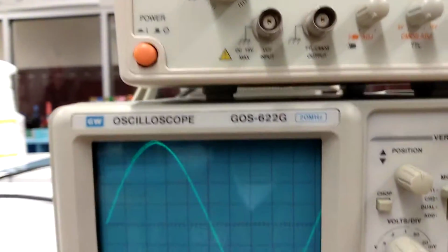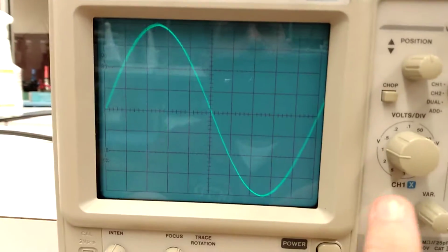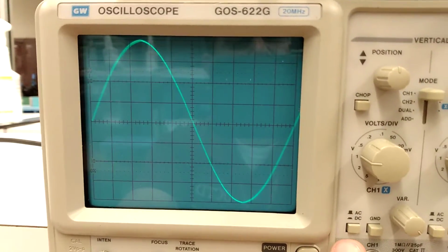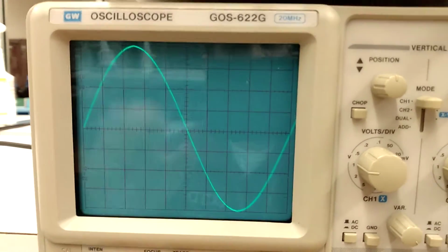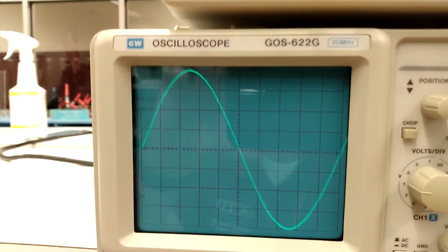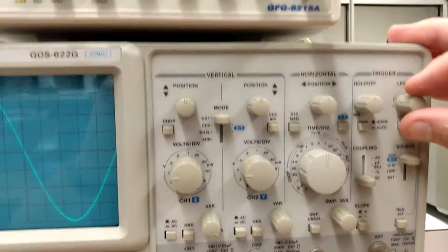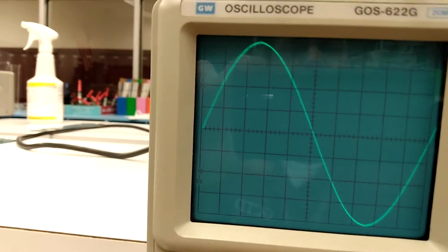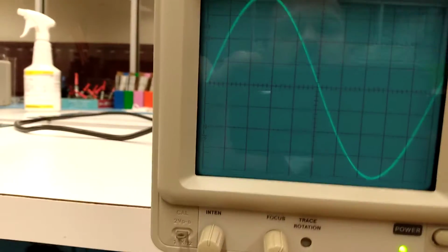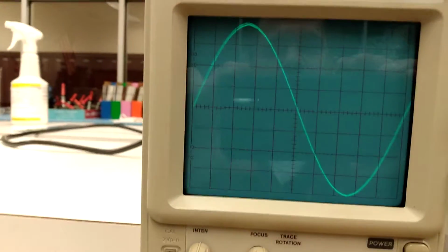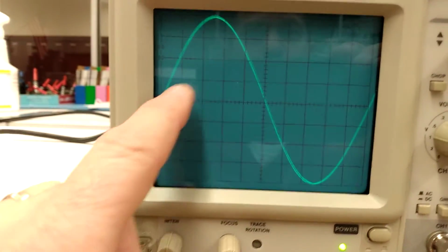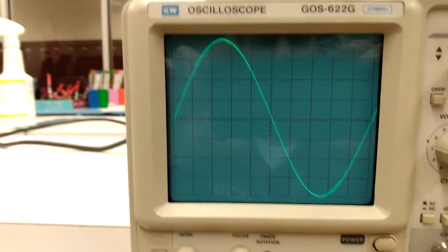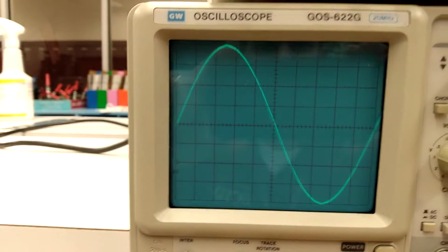And when we look at our oscilloscope, which has been set up now at 1 volt to the division, we've got a DC offset, so we're splitting our signal in the middle. Using our trigger level here, we've adjusted our pickup level so that it is right at the 0 mark there. And looking across, counting your number of squares, 1, 2, 3, 4, 5 squares for a half cycle, meaning you have 1 full cycle with 10 squares.